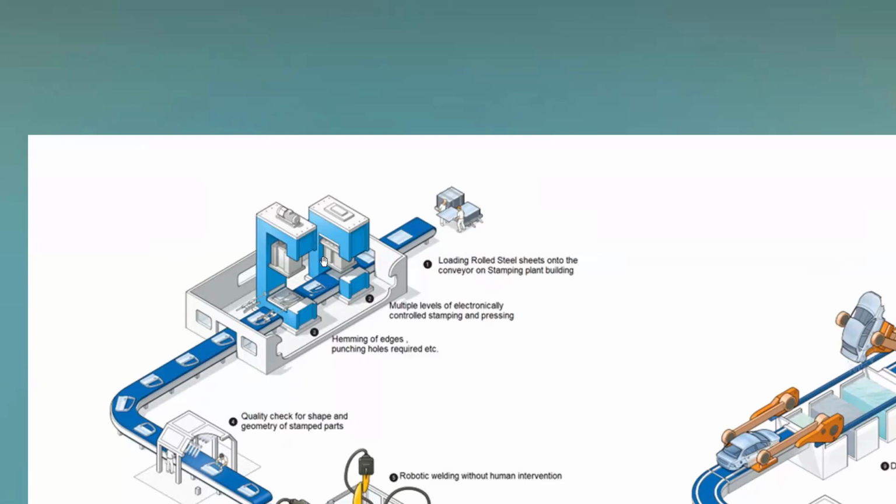First, they will have stamping dies, fixtures, etc. The sheets will go in, and the big stamping dies will stamp them into the required shape of, for example, a door, as you see here. At this stage, this is totally electronically controlled and managed in a computerized manner. Once the stamping is done, you will get the required shape, but with sharp edges.